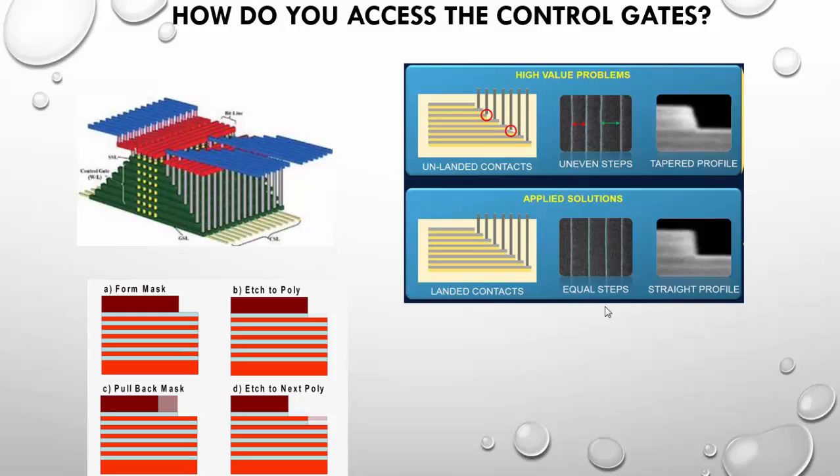Now we could etch each portion of the stair step, then perform a lithography step, then etch another, and so on. But this would create a ballooning number of lithography steps. While a typical NAND flash today might require about 35 mask steps, a 64-layer stair step would require 64 mask steps in addition to the 20 or more mask steps used to build the underlying CMOS control logic.